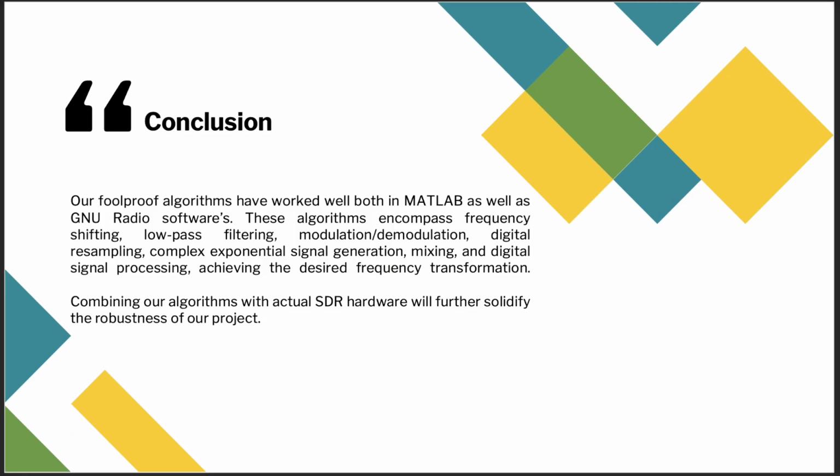The conclusion part. First of all, with the help of Matlab, we have successfully up-down converted audio and image data. Later, up-down conversion of an audio signal was simulated by using GNU Radio. And the most important part, the future scope of our project. We will be working with the appropriate SDR hardware and will use the SDR USRP source block in GNU Radio instead of the signal source block to create an open source RF up-down converter for satellite communication.